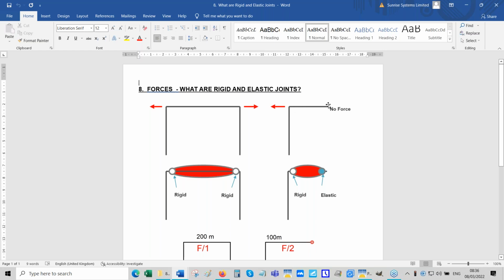We are not considering the external forces, which could be due to a multitude of items which are restraining the pipe. If it's a power station, it could be snubbers or something which are restraining the pipe. We cannot consider what force they're going to apply. We only consider the force exerted by the fluid. So here, this is rigid and that's elastic. Please understand this point, that there is no force acting in this way.